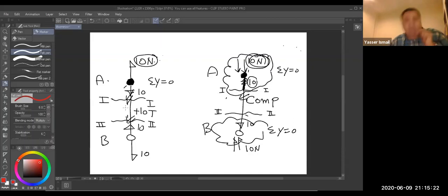If the internal force is pulling your finger, that means tension. If this force is pressing, that means compression. Compression is minus, and this is tension. I believe it's very easy, and you can solve. Let us have a particular example for a truss.